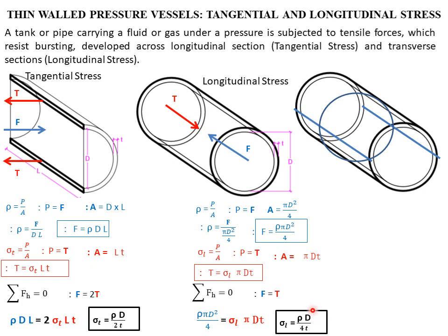of the vessel. So from this formula, we can say that the tangential stress is equal to twice the value of the longitudinal stress, since they have the same pressure times d, and the only difference is the divisor, which is 2 for the tangential and 4 for the longitudinal. So from these two equations, the tangential stress is twice the value of the longitudinal stress. And so we can say also that the bursting point of the tank is always on the tangential part, based on this formula.